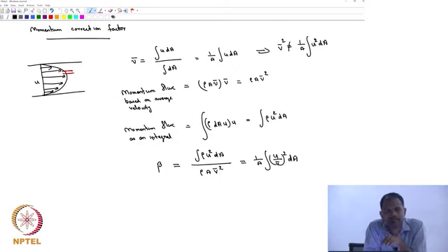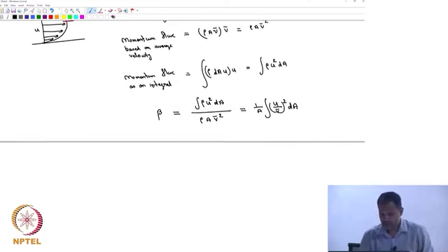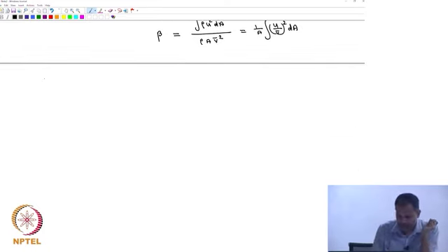We have made a similar error now in our energy equation also. Can you guess what that would be? Because we have estimated kinetic energy based on average velocity. Should we do that? Because we know kinetic energy can't be just average velocity square. In fact, let's try writing down what would be the kinetic energy, the flow of kinetic energy.